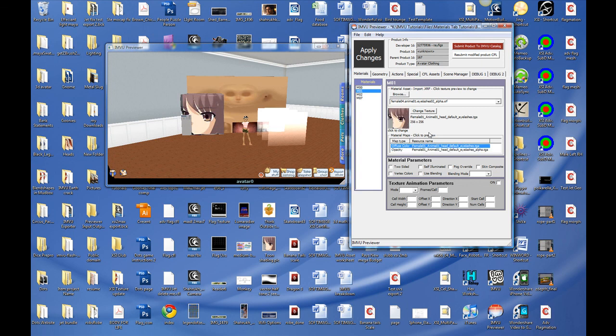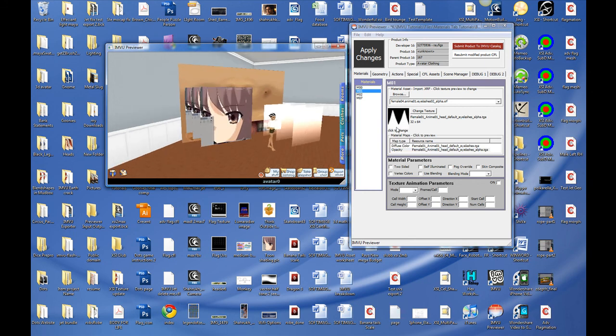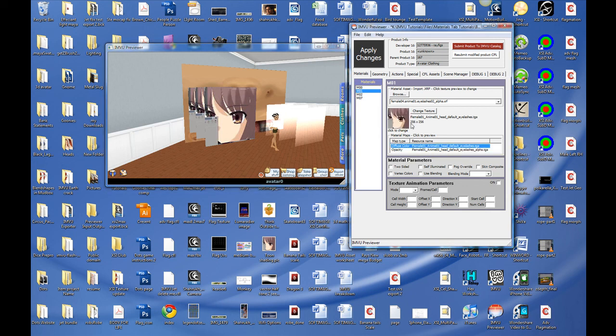Okay, so we're running into an issue here with the fact that our texture maps don't have the same proportions or same dimensions. So you can see I have a 256 by 256 picture and a 32 by 64 picture, and since they are not the same, IMVU is angry at us. That's something we can look into more later in the area with problems within the previewer videos, but in order to fix this, I need to make sure that this has the same resolution as this.